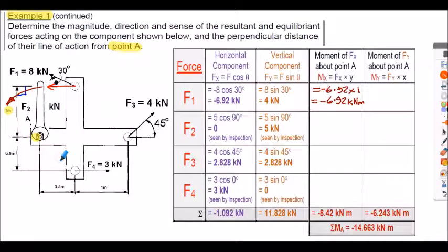Sometimes it helps by adding the spanner for the perpendicular distance to the line of action of the force. From the line of action, if we consider applying our force here at the spanner, we can clearly see it will rotate in an anti-clockwise direction about the nut shown here, which is point A, about where we're taking our moments in this case. So sometimes having our spanner positioned normal to the line of action of the force can help us in our understanding of evaluating the sense of the moment.